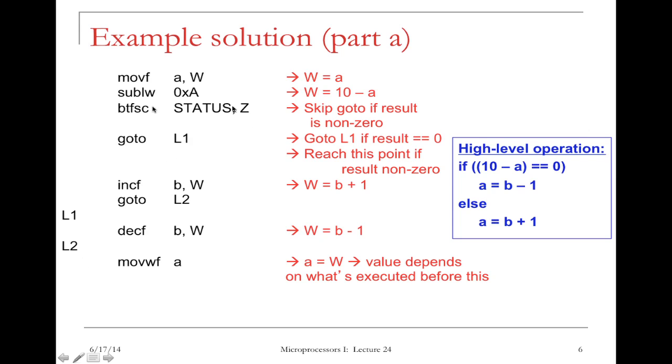Okay? Now let's come back here. If this variable A indeed has a value 10, or A in hexadecimal, so when you do the subtraction, you do hexadecimal A subtract hexadecimal A, that's a 0. So this subtraction instruction will set the 0 flag to be a 1.